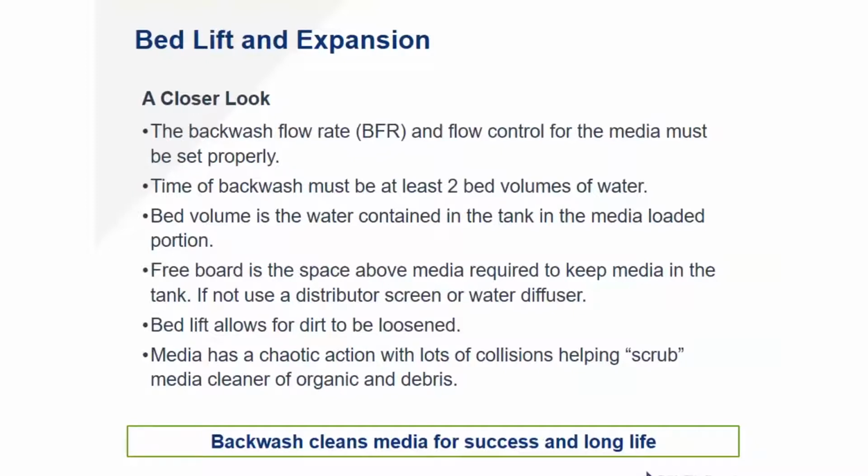Bed lift allows for dirt to be loosened and organics and things bound to the media itself to be scrubbed free by all these chaotic collisions. Think of a lotto machine, all the balls bouncing around. Every time a granule of activated carbon bumps into another, that force is knocking debris and scrubbing organics off the surface. So backwash cleans media for success and long life.